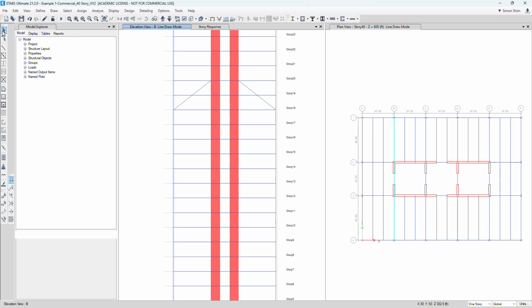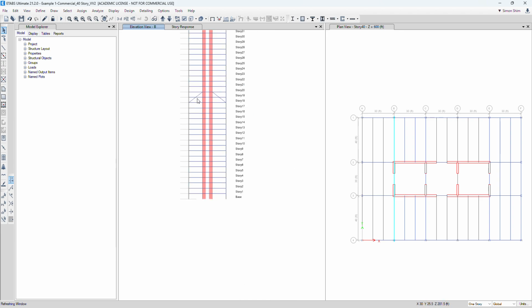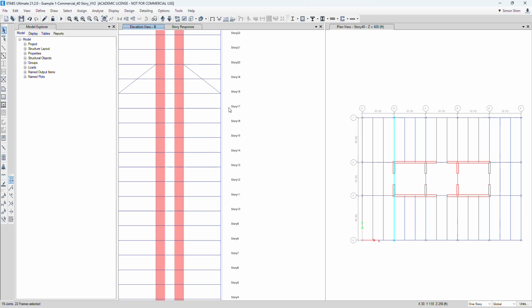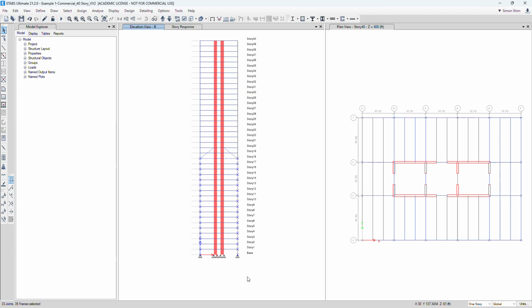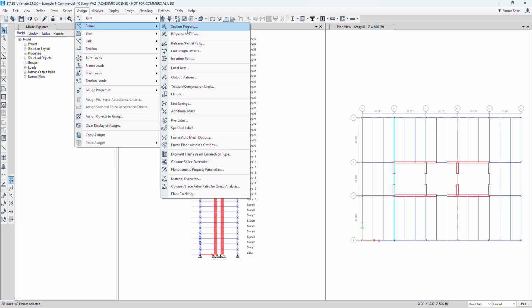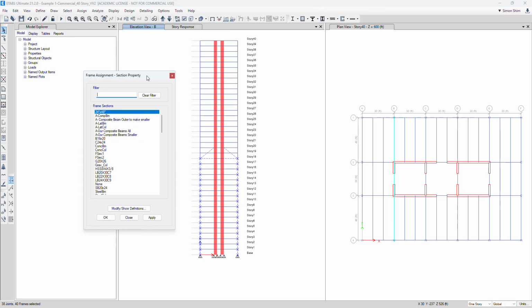So here, right? I'm going to choose here a diagonal bracing and this bottom chord, and then the column below here, the column below, I select. So I just choose a much bigger, heavy section for this. Just to make it simpler, but I think we have to optimize all these sizes. I'm just choosing W14x500.